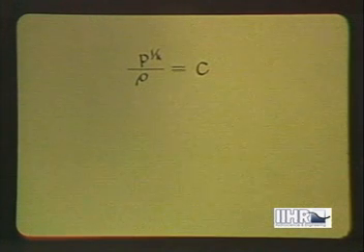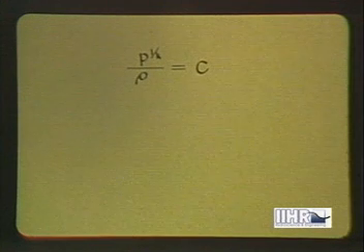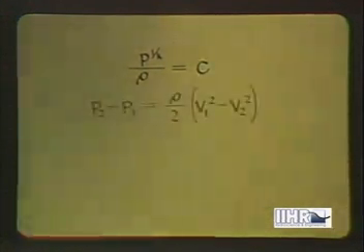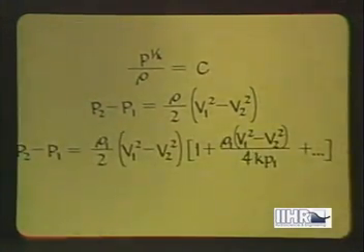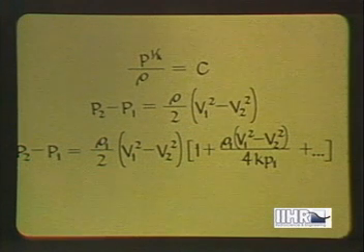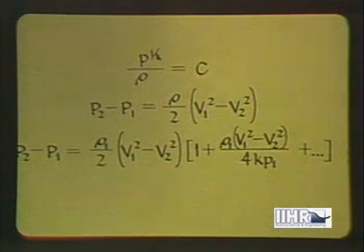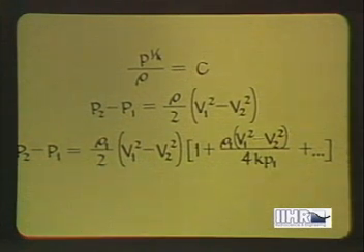If instead of the temperature, it is the heat content that does not change, the pressure density equation involves the adiabatic constant K. If this is combined with the equation of motion for negligible resistance, a result will be obtained which differs from that for an incompressible fluid by an amount depending on the density and the change in velocity between any two sections. In other words, in adiabatic flow, a pressure change introduces a temperature change, which augments the change in pressure.